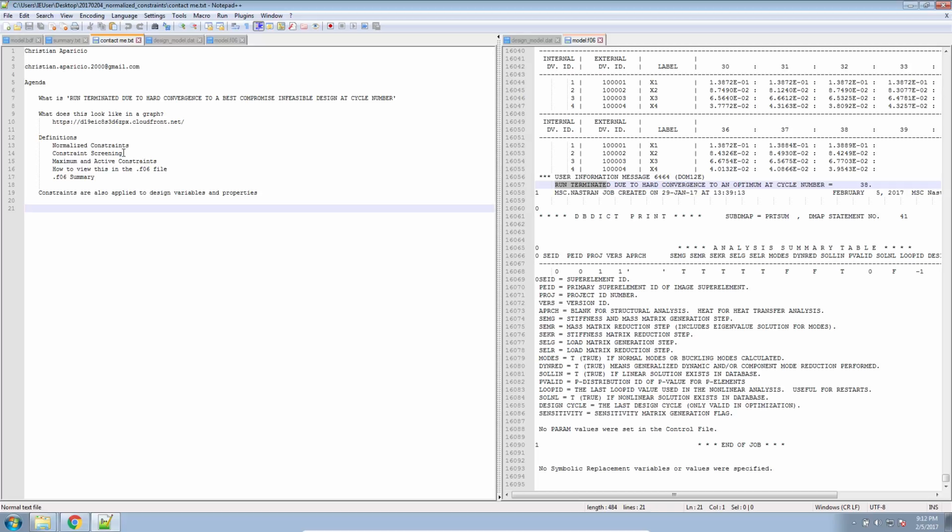And I should note that for each design cycle, the maximum constraint that dictates the optimization cycle will change from design cycle to the next design cycle. By this I mean in one cycle it could be displacement that's dominating. It's just being severely violated. But then the optimization fixes that constraint, but now the stress value is being violated. So you see that jump again and again.